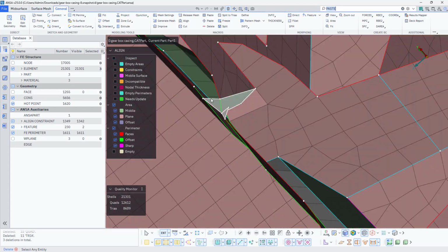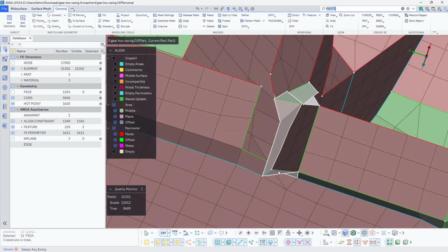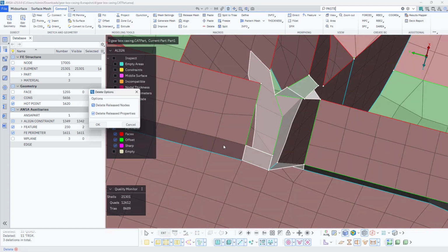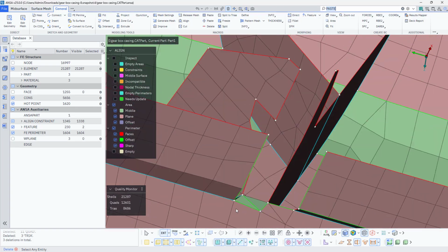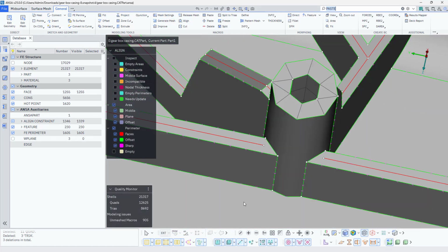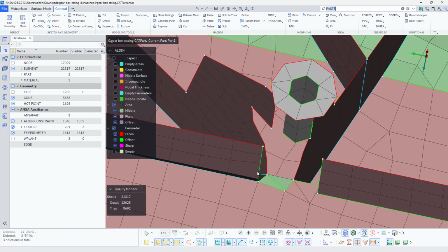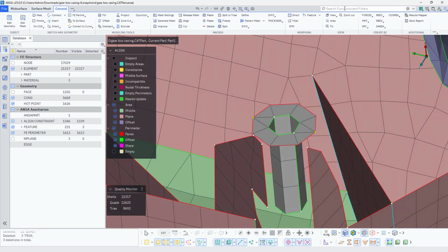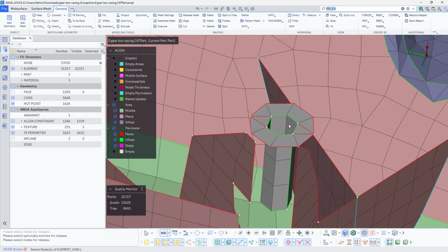And then these regions too, some of the elements will create issues while joining. So you can delete them, and then you can use the CAD and just generate the mesh only for the top region. By using the release mesh, you can release it. Now this is released. I would like to release the grids. So you know how to release them. Just select the grids and release them.